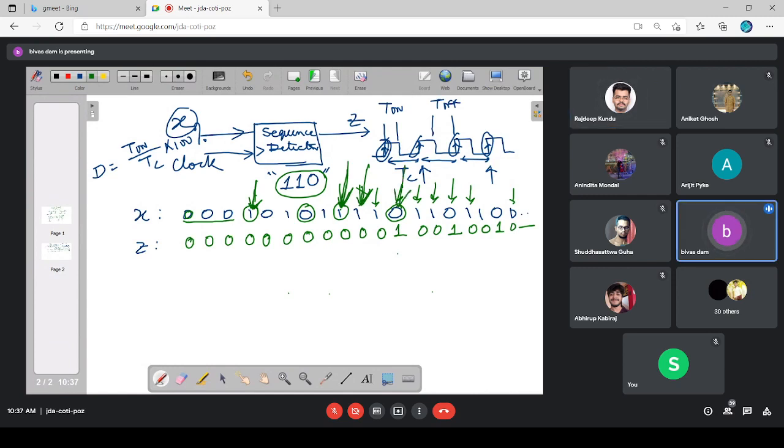Now, if I get a 0 here, what is the inference? Third bit. Sequence is complete. Why so? Because the first two bits of the sequence are already available. Okay. So this is the type of history that you have encountered in the sequence detection problem.